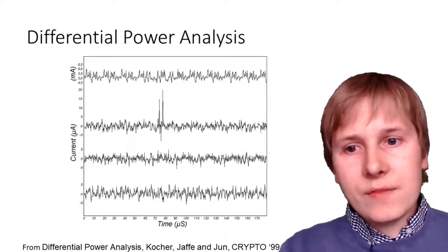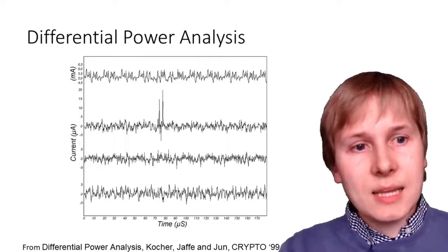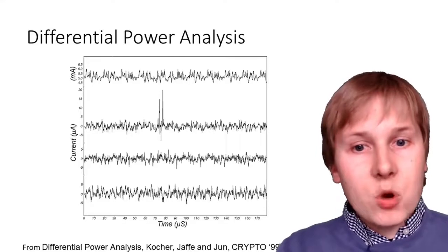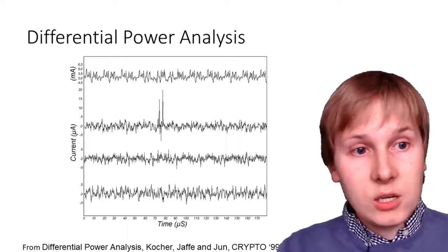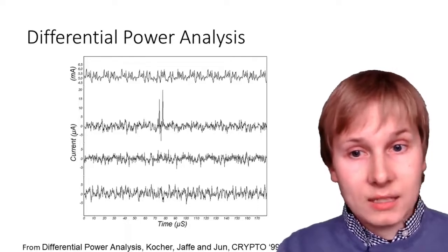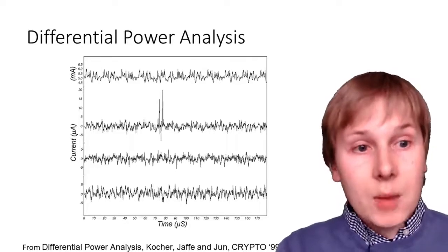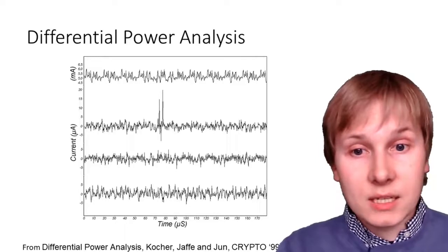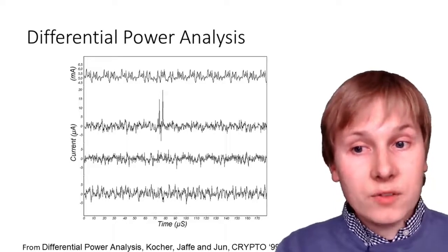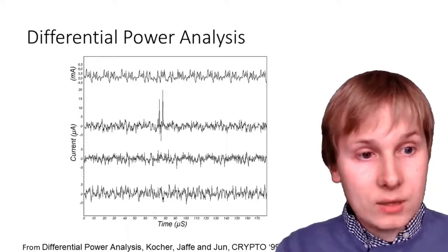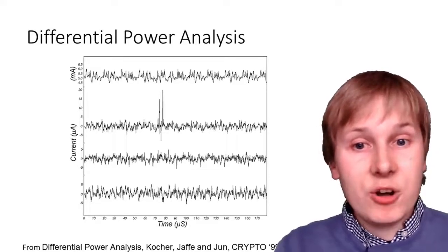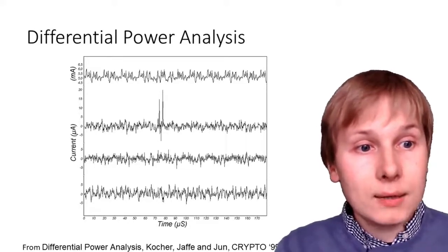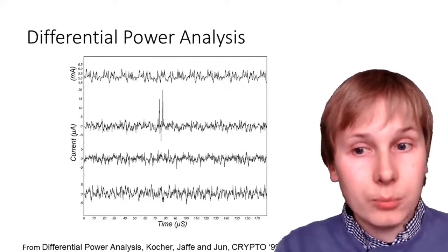This is true even if the algorithm is hardened against simple power analysis, by removing data-dependent control flow that gives away the secret. I.e. you can harden it against simple power analysis by doing that, but not differential, because if you have enough copies of the signal, you can overcome the noise enough to measure even very fine-grained power differences, caused by adding together different numbers using different amount of power, let alone taking different branches, for example.